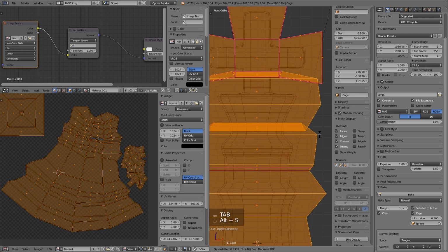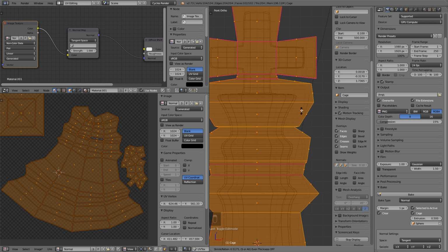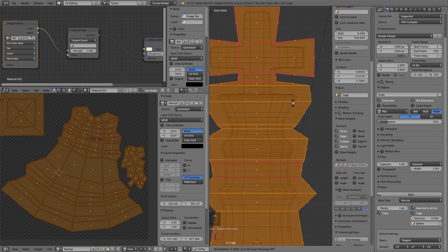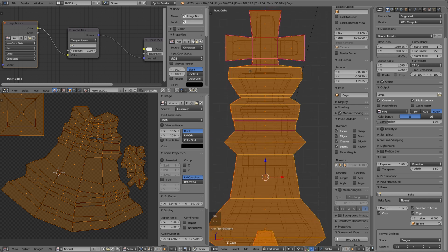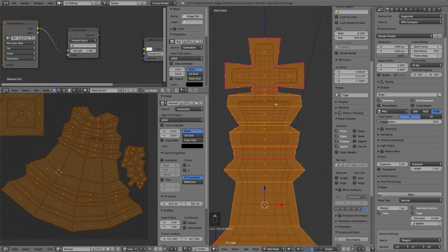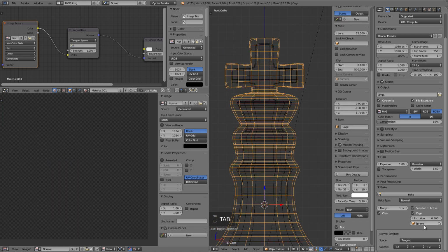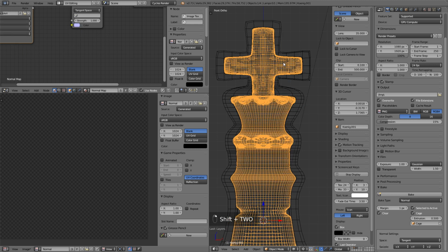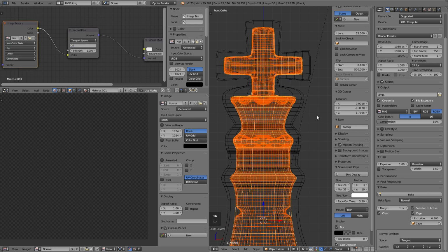Right now this would be an extrusion that would be too much. They intersect, and this is exactly what we saw when we set the extrusion to 5. And you can plainly see that with this method I have full control, and I can check if there are any gaps or overlapping parts of my object. For this to work, I obviously need to select the cage object, and then let's bake the high poly, shift select the low poly, and bake again.